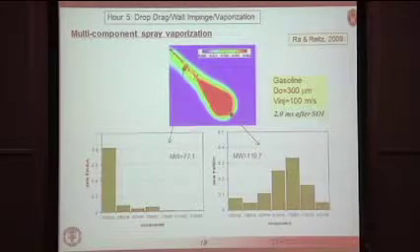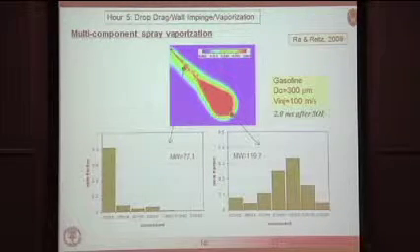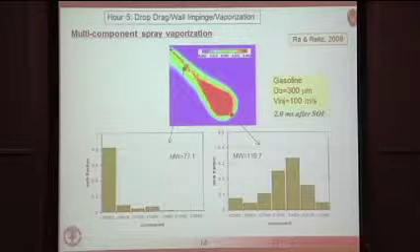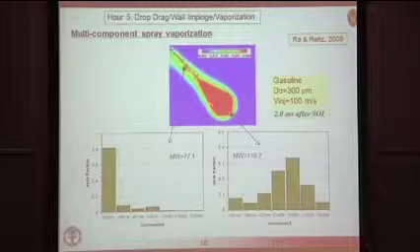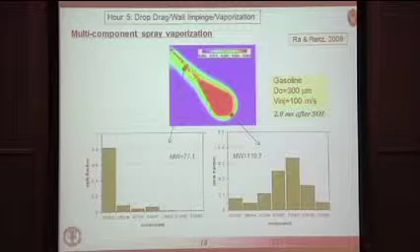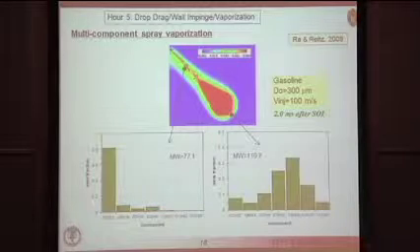So basically, if you're looking at a combustion situation where ignition delay depends on the type of fuel that you are looking at, you might expect that the ignition is going to take place at different locations depending on how much of the more reactive fuel resides at that location. So it's very important to take into account this type of differential vaporization process.